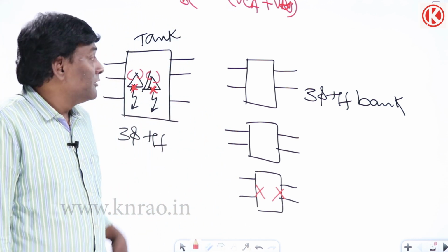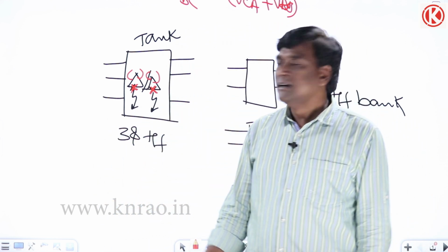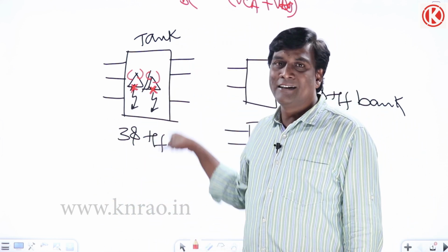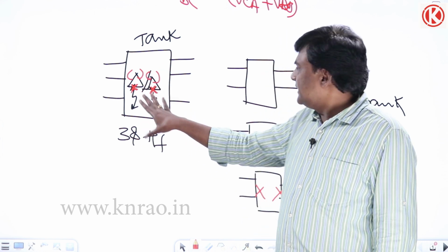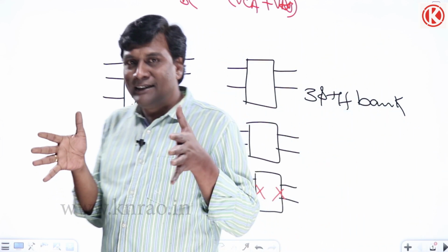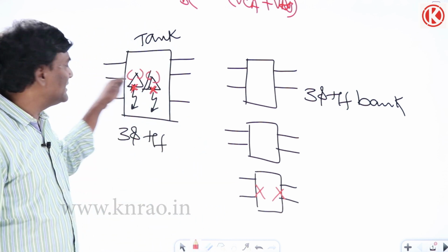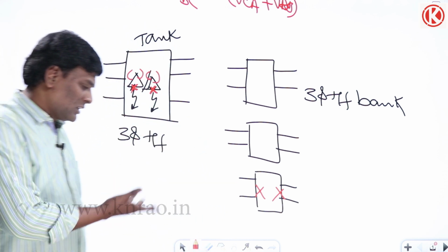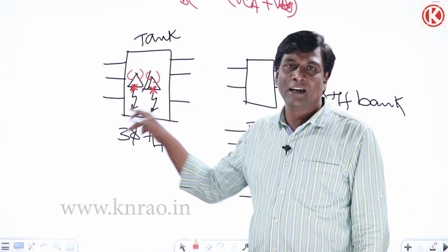Now in this case, for example, if the three-phase load is maybe 10 MVA, up to 3 MVA in a single transformer tank I can design. Okay, so in a single transformer tank, 3 MVA is the maximum capacity, meaning that each and every phase has to bear roughly 3 by 3, so 1 MVA has to be delivered.